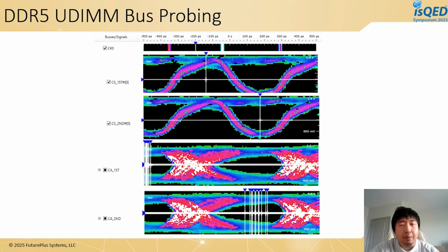This technique was able to debug DDR5 UDIMM very effectively, but the thing is, most of the important use cases with DDR5 memory, like very sensitive use cases, like what I mentioned, medical, security, financial, those cases with sensitivity for data integrity usually use DDR5 RDIMM, since they are naturally more robust with the RCD on the DIMM. So for DDR5 RDIMM, things are quite a bit different.